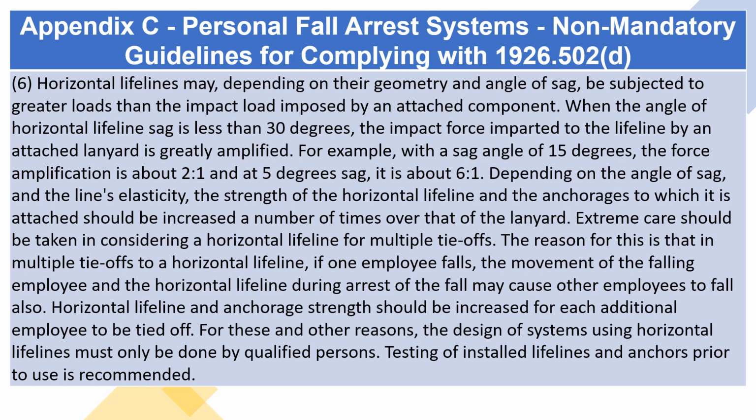Extreme care should be taken in considering a horizontal lifeline for multiple tie-offs. The reason for this is that in multiple tie-offs to a horizontal lifeline, if one employee falls, the movement of the falling employee and the horizontal lifeline during arrest of the fall may cause other employees to fall also. Horizontal lifeline and anchorage strength should be increased for each additional employee to be tied off. For these and other reasons, the design of systems using horizontal lifelines must only be done by qualified persons. Testing of installed lifelines and anchors prior to use is recommended.